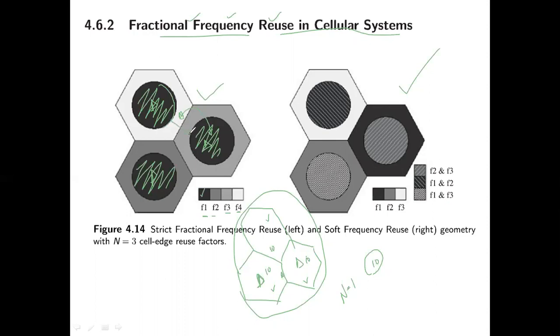See here, now the distance. If I have to represent this with conventional cellular communication with a cell frequency reuse factor of 1, then maybe I would represent all 3 of these hexagons with completely black color. But here you can see what has been done. The inner circle only, only at this particular distance. That means whenever these particular frequencies are being used, it transmits them with very low power.